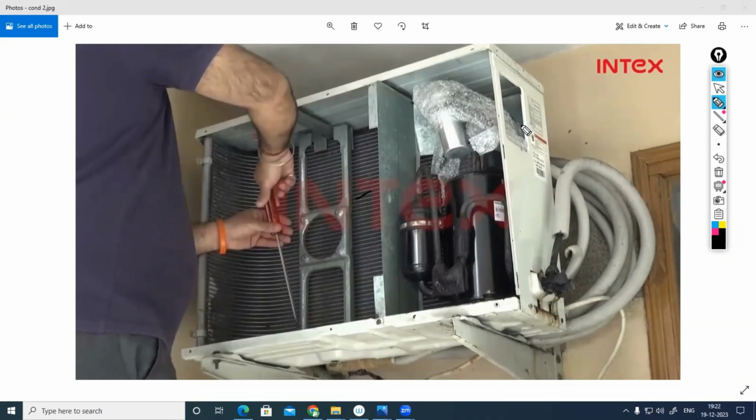Correct. Then from the indoor unit to the outdoor unit, after extracting the room heat, the liquid refrigerant will be evaporating to vapor, or sometimes with respect to the heat within the space, it might be superheated vapor. If it is getting excess heat, it will become superheated vapor. That vapor only will be coming back to the outdoor unit.